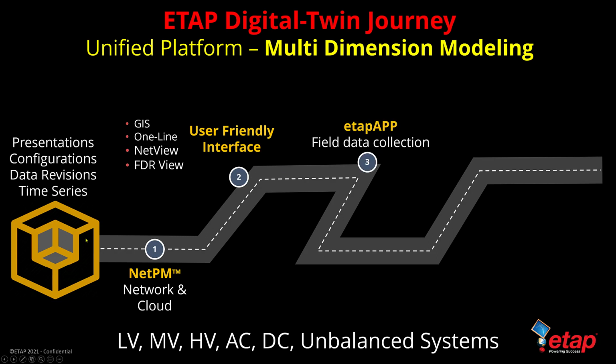This model data is improved by the ETAP app, where your field electricians can go out, collect the data, and automatically synchronize that back to the model and validate some of the key information. In case the data is coming in a manner that is not carrying any geospatial or logical coordinates, there's also layout routines within ETAP that automatically lay out the single line diagram based on user-defined rule books.